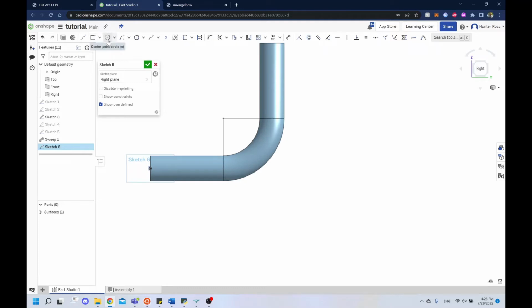probably, best way to do this would be to make another circle, or we could do another arc. Because if we tried to do this by just doing this, it's not exact. We want this to be exact, and that's very important for OpenFOAM. So maybe we defined another sketch, and then from there make it connect. Or maybe what would be better is using an arc. So let's try that instead.